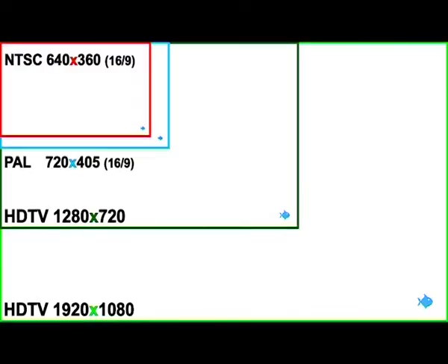This standard, which was slightly modified from both the Digital Television Standard and the Digital Audio Compression Standard, moved US television from an analog to digital standard. It also provided TV stations with sufficient bandwidth to present 4 or 5 standard television signals or one HDTV signal providing 1080 lines of resolution with the movie screen's 16:9 aspect ratio. This aspect ratio allows the viewing of CinemaScope and Panavision movies.